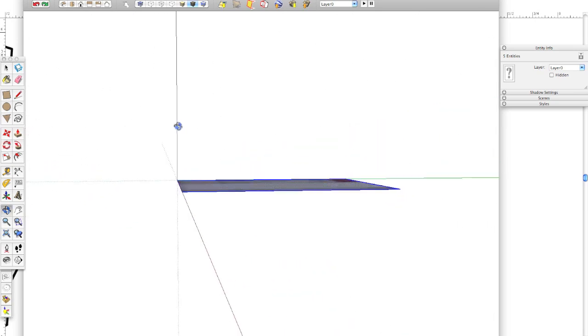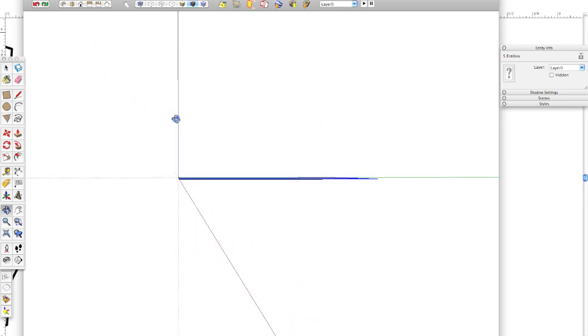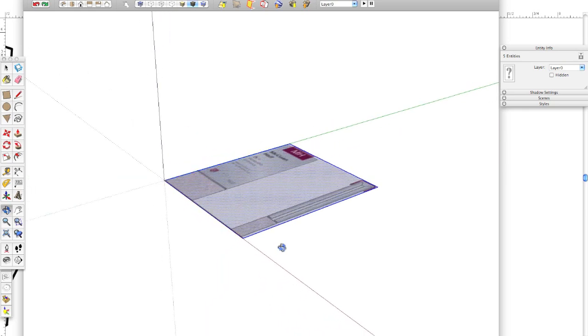Now if I'm lucky, I can sort of orbit this way to get the red axes to orbit from. Or instead of clicking on the first click, if I click and hold or click and drag out towards the red axes, it'll actually flip the orientation of the protractor here.